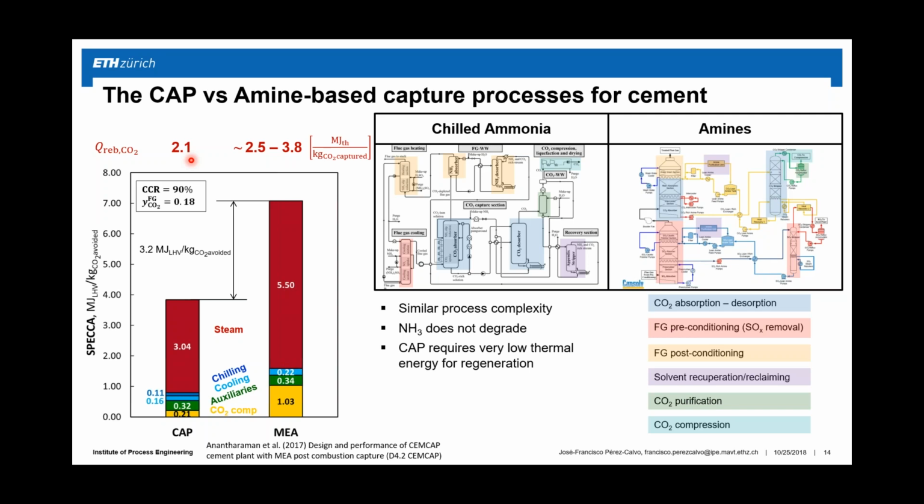But this doesn't mean that this brings a much higher packing for a CO2 absorber. For this work, indeed, we have obtained a length of the packing for the chilled ammonia process of 23.5 meters, while in the literature for amines, we find values ranging between 10 and 30 meters. Additionally, ammonia is globally available and has a lower environmental footprint and cost compared to amines.